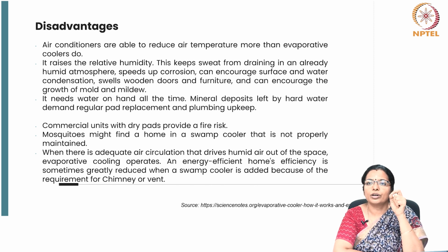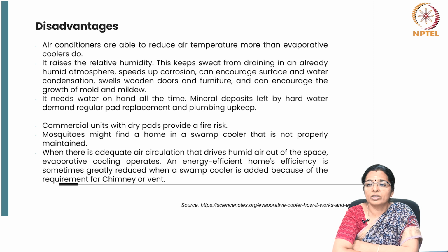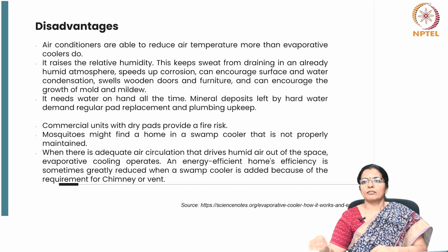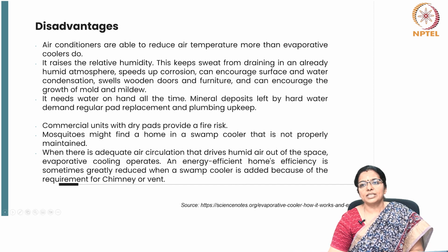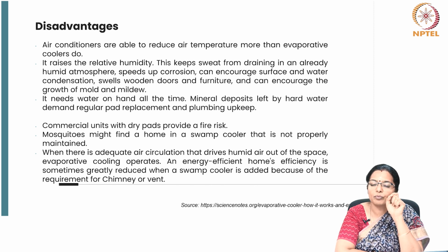It needs water on hand all the time. Mineral deposits left by hard water demand regular pad replacement and plumbing upkeep. The commercial units with dry pads have a small disadvantage of being fire prone.